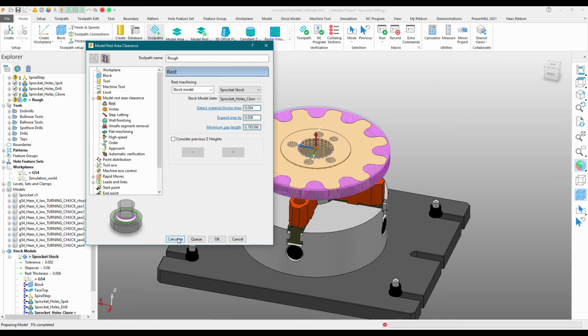So if you're not familiar with the adaptive roughing strategy, it's just the ability to take a full depth of cut with your cutting tools with a smaller radial side cut. You're able to take a consistent feed rate, and you're never really going to break the engagement angle of the tool. So this, you're going to get better tool life and better surface finish.